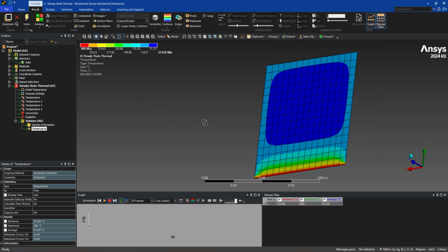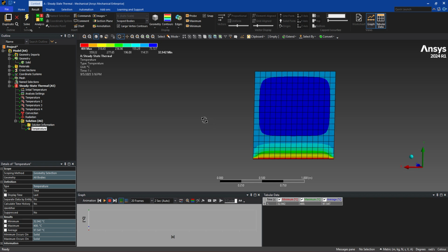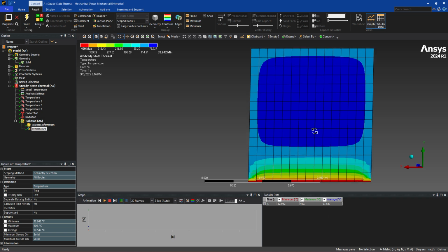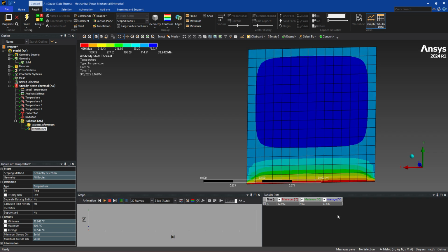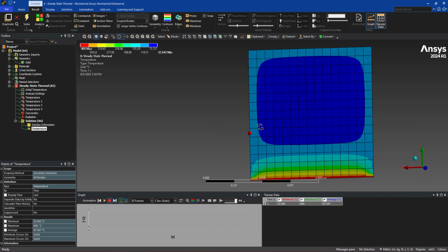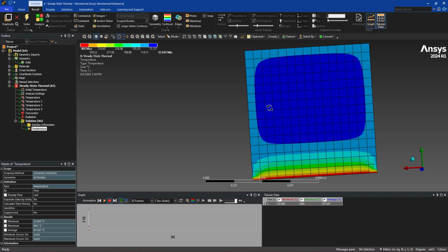So if you consider the convection and radiation heat transfer modes as well, the temperature distribution looks like this, and the average comes out to be 97.547, whereas for the 2D case the average temperature was 147 or something like that. So you can see a very low average temperature, because heat transfer will also be occurring through convection and radiation, and thus it should be the actual heat transfer for this thin plate if we consider the outer environment as well.